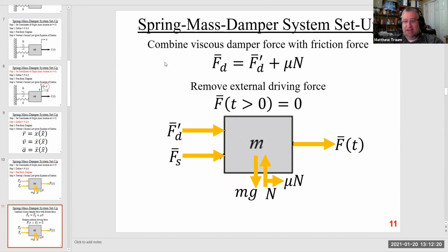because that's essentially what these terms do, is they prevent the mass from just oscillating back and forth forever, right? And that's because they provide a dissipation quality that takes the energy that otherwise would just be oscillating between kinetic energy in the motion of the mass and potential energy in the storage capacity of the spring, and they convert that energy into heat, and then dissipate the heat out of the system. And so over time, the dashpot and the friction force will reduce the overall energy in the system and cause the mass eventually to come to rest.